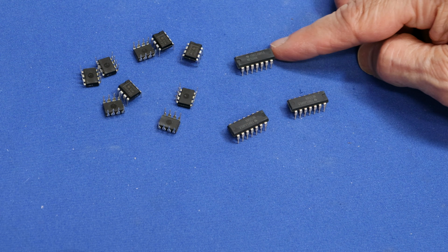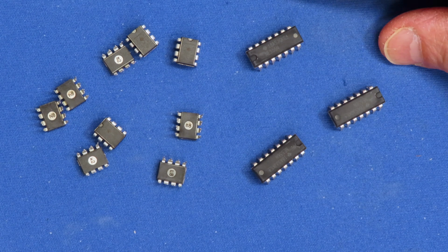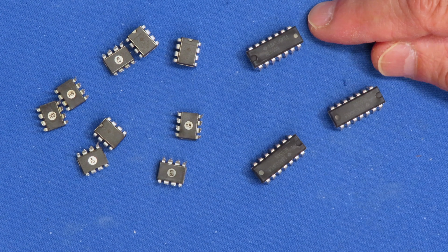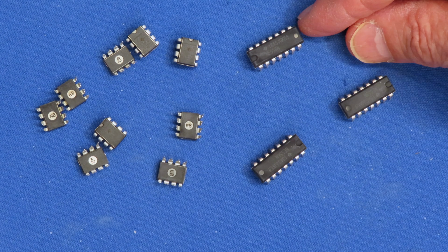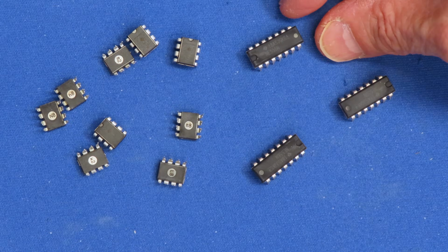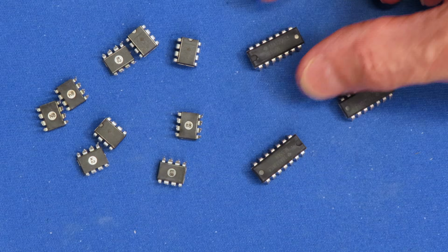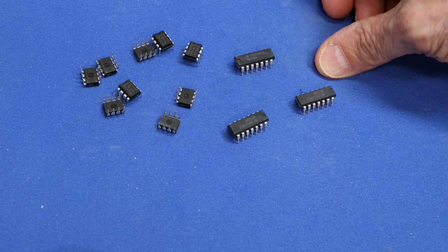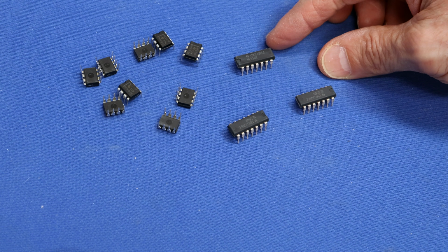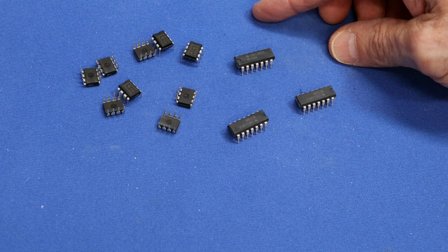I also have these chips over here, and these are 556s. A 556 is just two 555 timers in the same package. This is a 14-pin package. They've got all of the pins of the 555, plus the power and ground is common to the two internal timers. So the VCC and the ground pins, there's only one set of those, and there's a dual set of everything else. So if you're ever building a project that uses two 555s, you could always use a 556, and that would work out just fine. And it might be a little easier for you to breadboard that or to build a printed circuit board around it. But otherwise, as I said, there's not really much to look at.